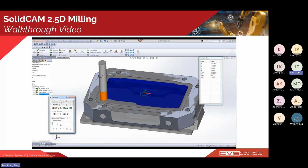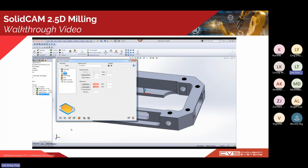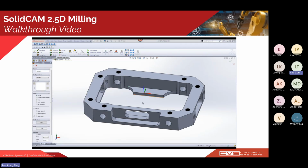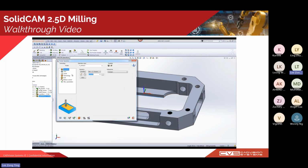So we'll go ahead and see the simulations to check for any collisions, any unwanted movements. Okay, once we are satisfied with this, what if we want to reuse these operations for another geometry? We can directly save and copy, and it will read those parameters from the previous operations and bring them to another operation.